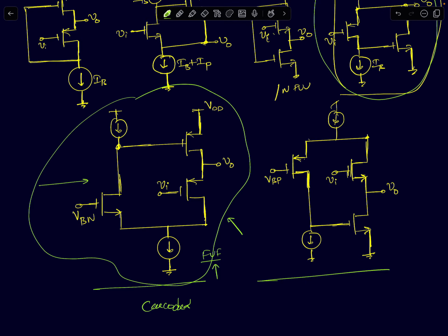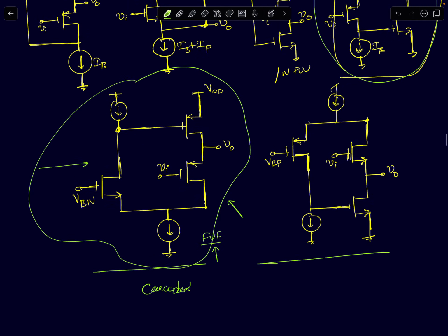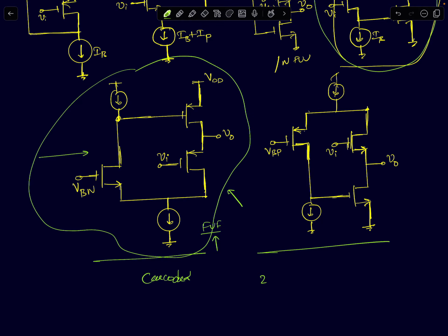I'll probably someday, if I get time, float a proper course on LDOs. LDOs have gone through a very interesting revolution in the past 20-25 years. We have gone from designing multiple stages. In the early 2000s to late 2000s, the whole decade, there was this sudden craze for low voltage designs where we had to go for multiple stages of amplifiers to achieve very high gains.